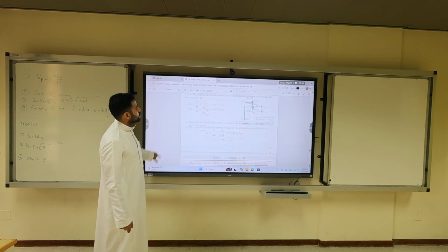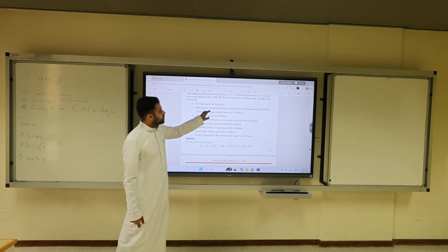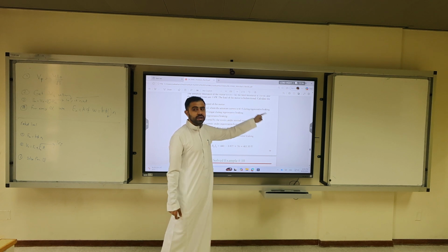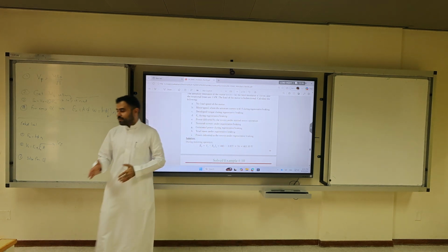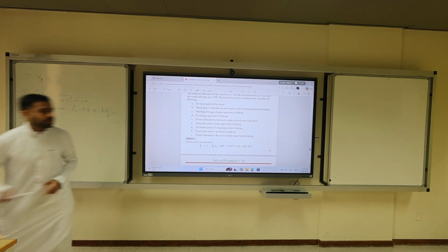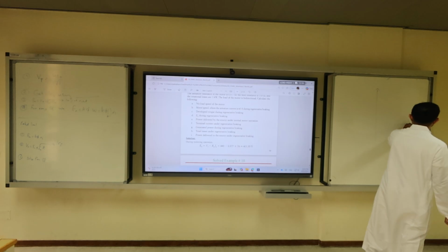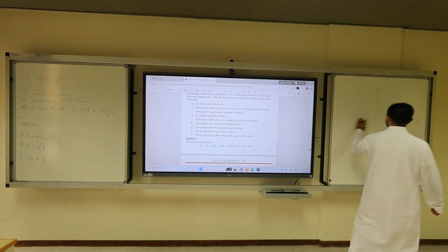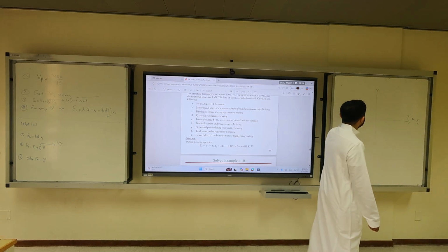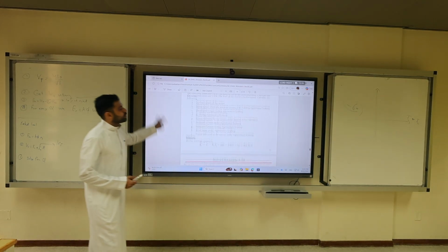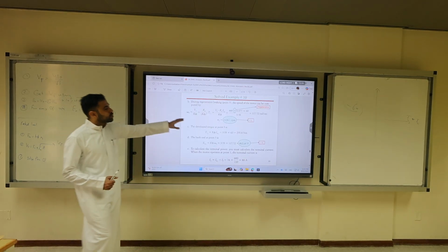Then part 2, motor speed, where the armature current is 60 amps during regenerative braking. So regenerative braking, what quadrant is that? 2 and 4. Quadrant 2. And remember, what was the x-axis? Torque or current. So if it's in the second quadrant, that 60 will be minus 60. It's regenerative braking. Because it's minus 60, you do the math.